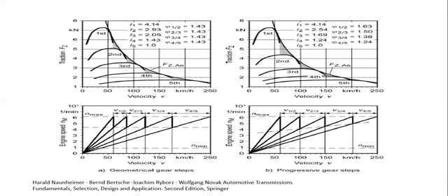In low range gear step 1 to 2 will be a little bit too small, but the problem won't diminish during the upshifting because gear steps get smaller and smaller due to the progression. So every gear step in low range is too small. The better conclusion for using this will be, as long as the number of gears is 7 or less, the best solution is the progressive gear steps.